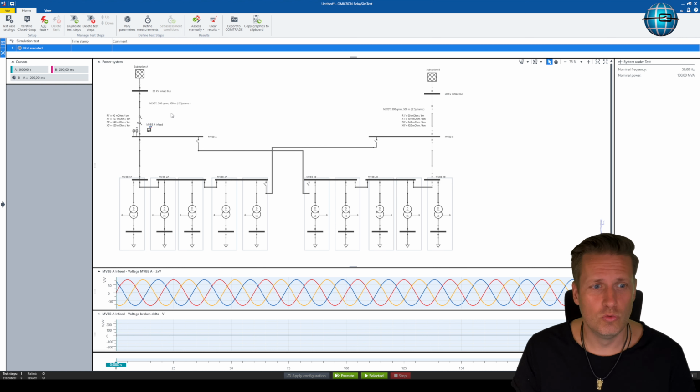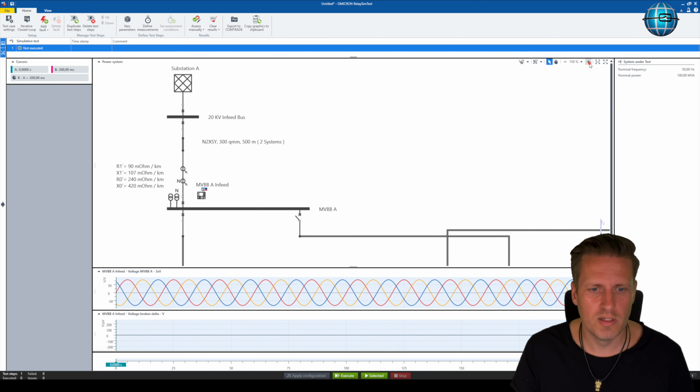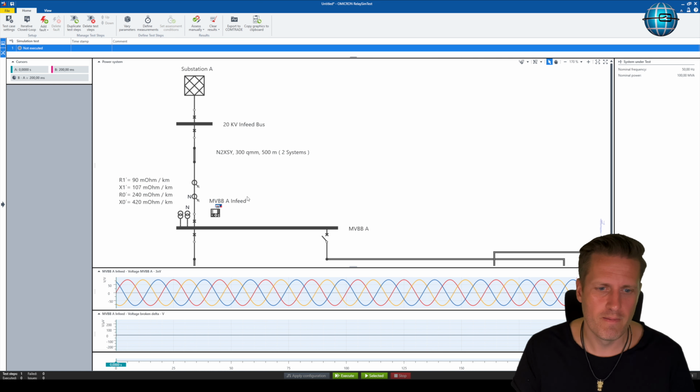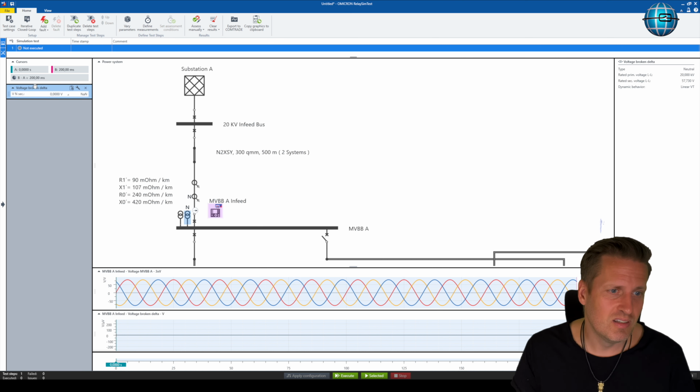What we first want to do is, on this blank left side here, we are able to arrange our measurements for the CTs and for the relays and so on. And for that, we just have to, let me just zoom in a little bit so that I can show you this much better. Let's get started with our zero sequence voltage, or with the broken delta voltage that we measure for the entire bus bar. And you have here this little pin symbol, and just click on this needle, and here the measuring will appear.